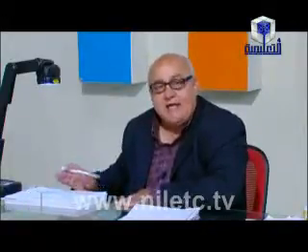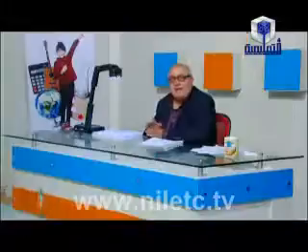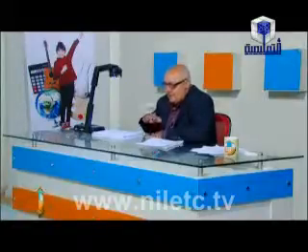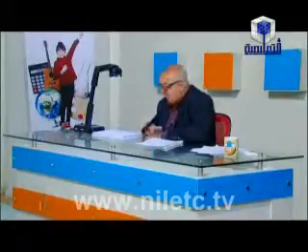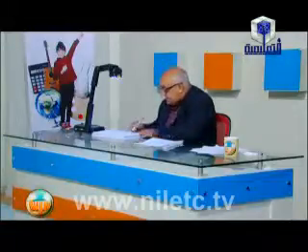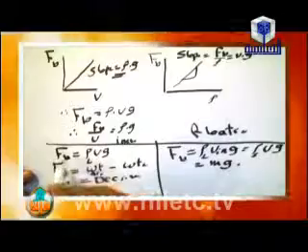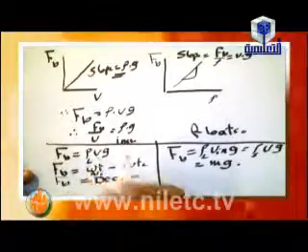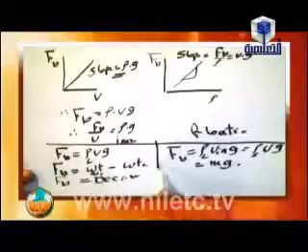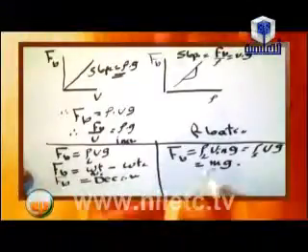But the difference between them is the volume immersed. If the density of the liquid increases, the volume of the immersed part decreases. If the density decreases, the volume of the immersed part increases. So we have two cases in Archimedes: FB equals rho liquid V g, and FB equals weight in air minus weight in liquid, which equals the decrease in weight.